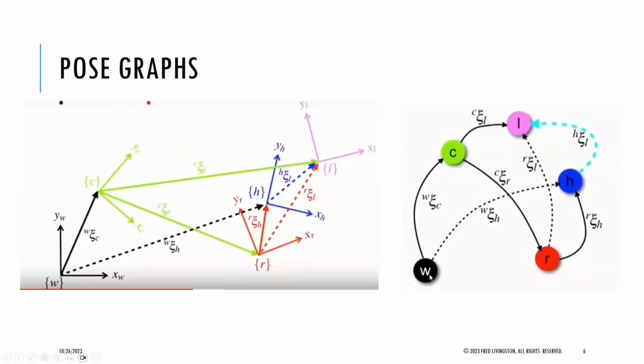And so here is an example. Here's my world frame, or sometimes they call it origin, and sometimes it's called a home position. And here is where my camera is located. This system has 2 arms, a left arm and a right arm, and H is my object. If I want to know where the object is located in XYZ and its orientation, roll, pitch, and yaw, in reference to the home, the world is where we start. And then this is the transformation to home. This is the position, and it's going in this direction because we're going from the world to the home, so the arrow is pointing that direction here.